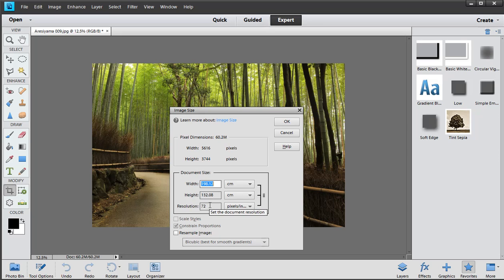It's ridiculous. I don't want to print a 2 meter wide picture. I haven't got a printer that big. So I'm going to say let's just change the resolution to 300 dots per inch. And the reason I do that is you just push the pixels closer together. Because they're closer together, when you zoom in, they're very high resolution and are perfect for printing.